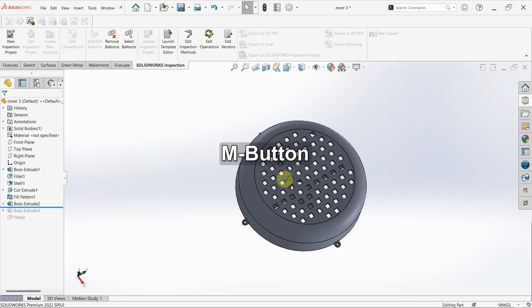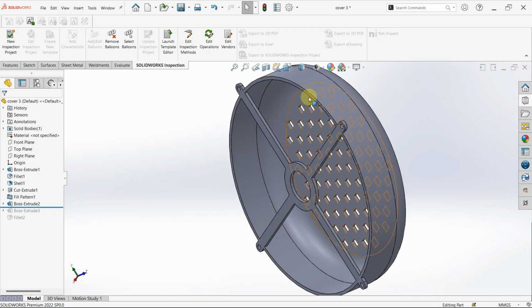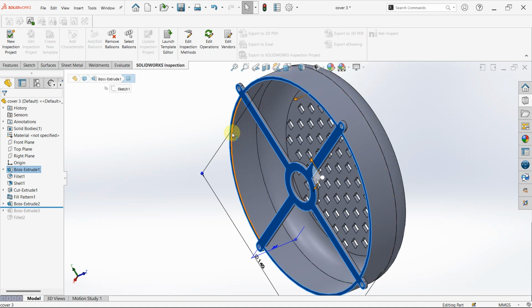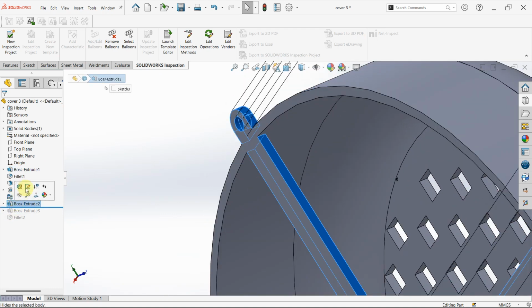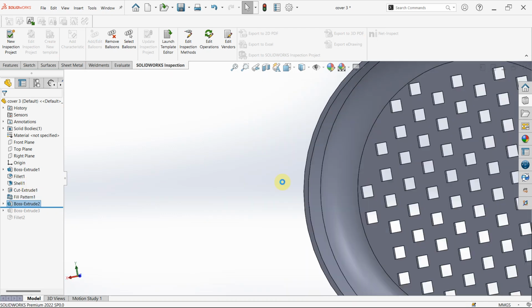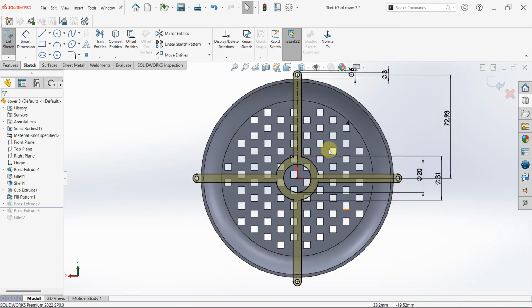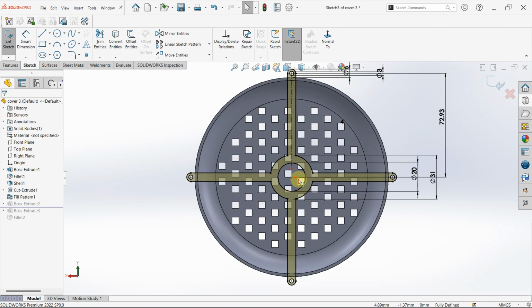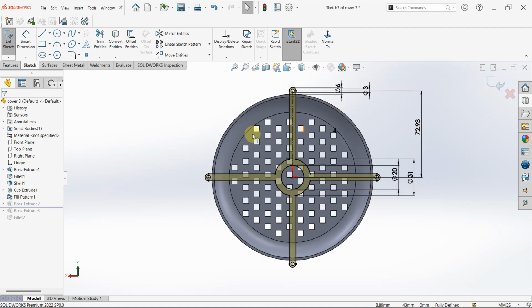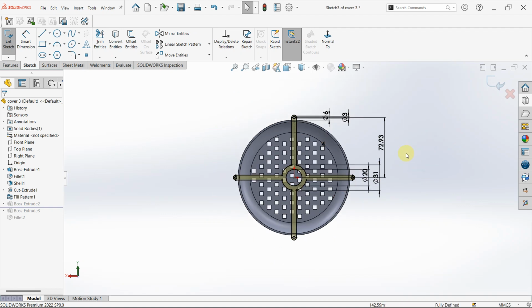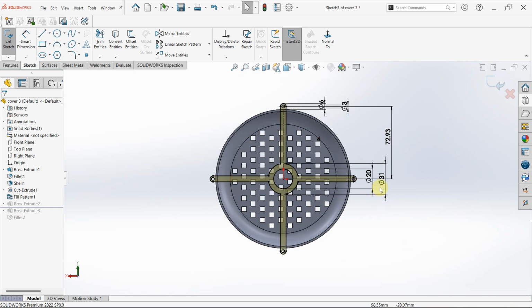Then it was extruded for this. So this surface was used as the sketch plane. Okay, and then we have the sketch. So this is the circle, and then you have a chamfer here, offset, and then probably copy this to this side, or you can just define one and use circular sketch pattern to copy it to the other side.